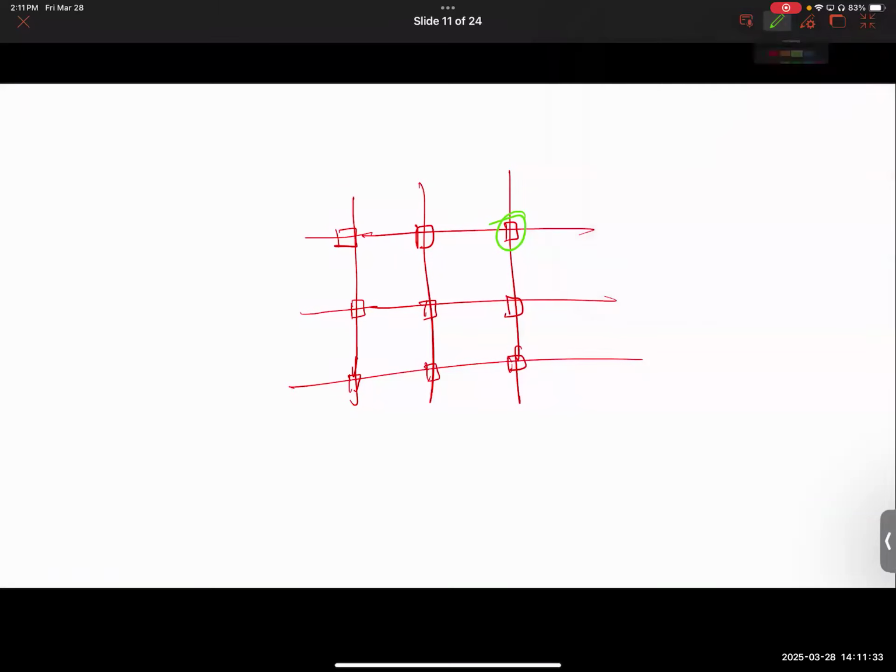Okay, so you want to access the green one. So what you do is you apply full voltage V and 0 across the cell. So that means this cell gets V across it, the full voltage, read or write, whatever, access voltage. Now, the problem is these other cells will also get V unless you do what? Unless you do V over 2.